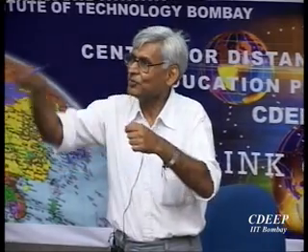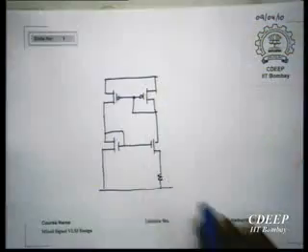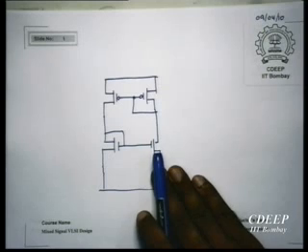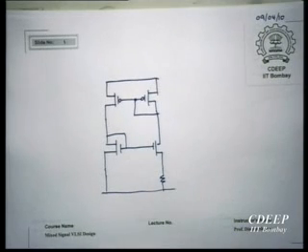In some sense, this circuit is what a flip-flop is in voltage mode. In voltage mode, 0 feeds a 1, 1 makes it 0 again, so the two live happily with each other. Essentially it is the same thing. There is this current mirror. Let's say that these two are matched. In reality, when we make the beta multiplier, it will not be matched, and forget this resistor right now. So then it is truly a current mirror feeding a current mirror.